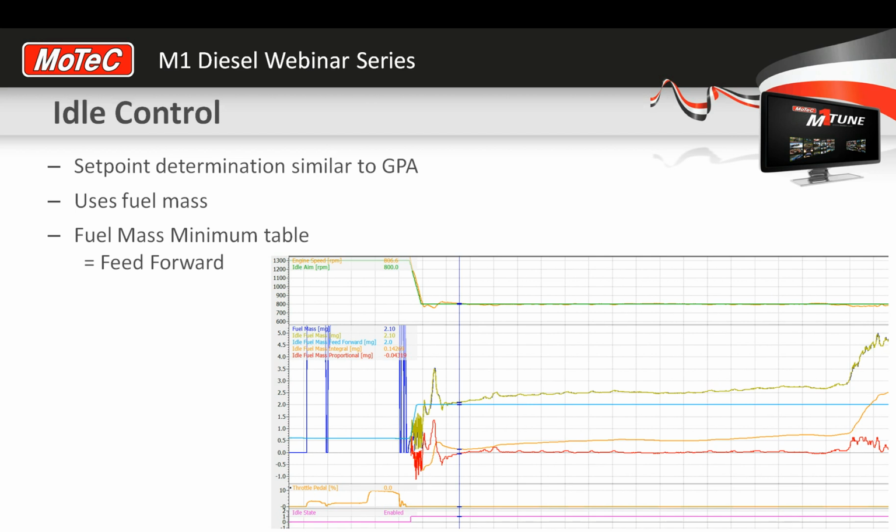So with a diesel, as we've said all the way through here, your power at the engine, at the crankshaft, is determined by fuel. It's affected a little bit by air, but not that much. Basically, add 5% fuel, get 5% power. Take 5% fuel out, lose 5% power. So the ECU has really good control of the amount of power it makes under idle control situations. If it wants to lift, it can calculate on the fly very quickly if it's under or over the aim, and it very quickly can change the amount of fuel.